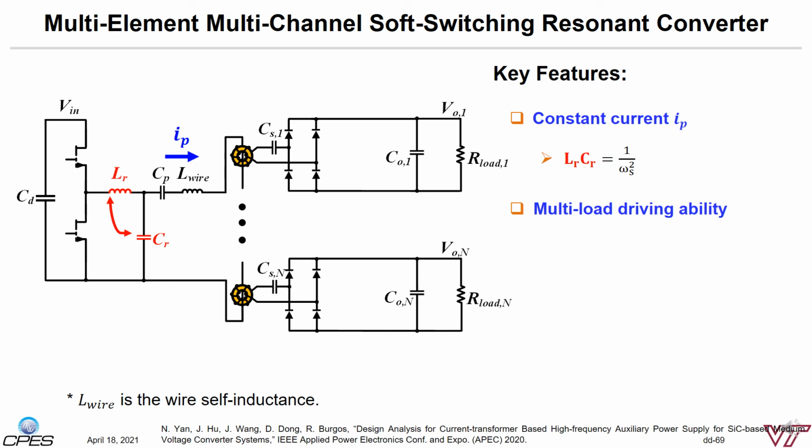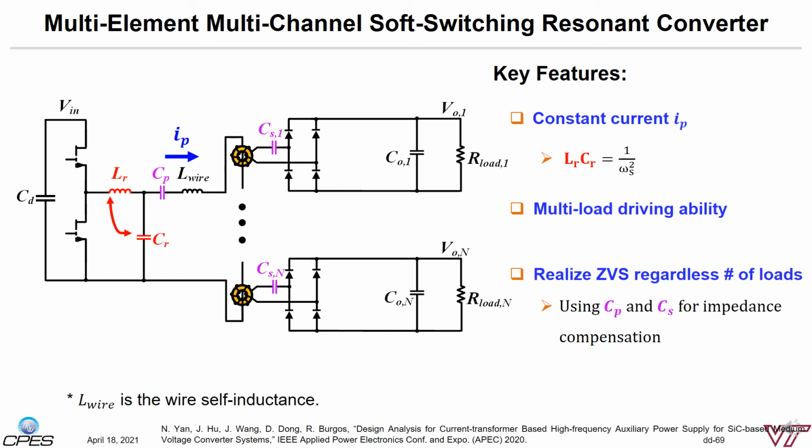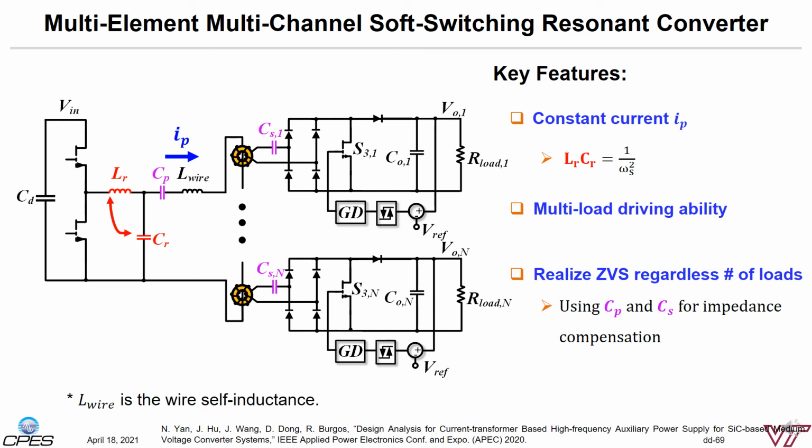The primary side winding is a single-turn design, so it can simplify the installation process and maintain a high insulation integrity. The ZVS source switching can be realized by the resonant component in each receiving circuit and make the system operation consistent under different numbers of loads. Each receiving side has its own regulator stage to regulate the output. In addition, the regulator will make the system fault tolerant. When any load has an open circuit fault, the regulator will automatically bypass the channel and keep other loads unaffected.